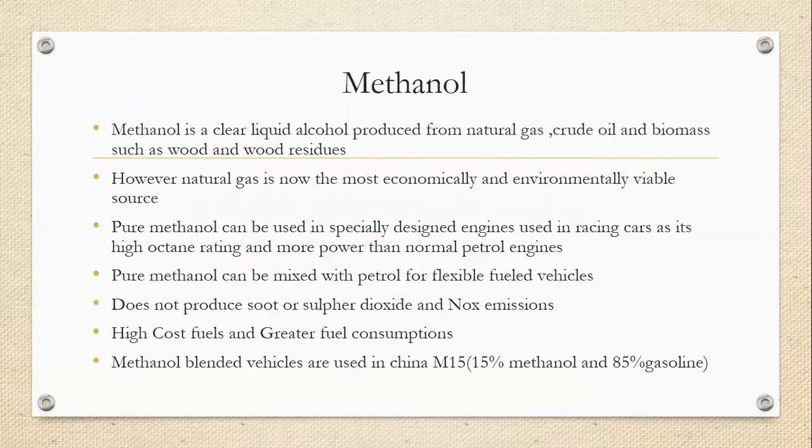Next, we shall see about the next alternative fuel, methanol. Methanol is a clear liquid alcohol produced from natural gas, crude oil, and biomass such as wood and wood residues. However, natural gas is now the most economically and environmentally viable source. This pure methanol fuel can be used in specially designed engines used in racing cars as it has a high octane rating and more power than normal petrol engines.